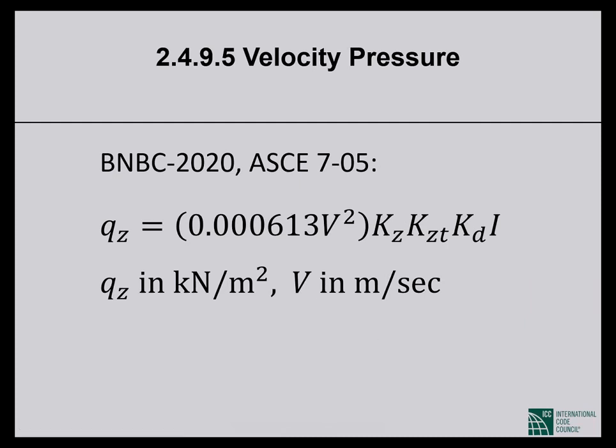So what we have within parentheses is 1/2 rho v squared. And the significance of that term, I will explain a little bit later on. So for now, 0.00613 is 1/2 of the density of the air in the proper unit. And these units in metric, I have problems with, but it can be figured out.